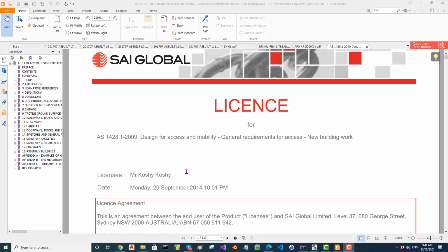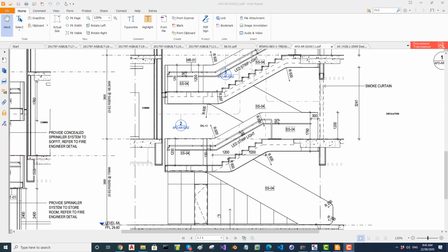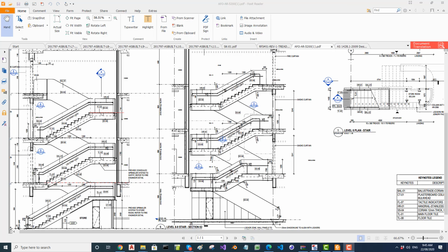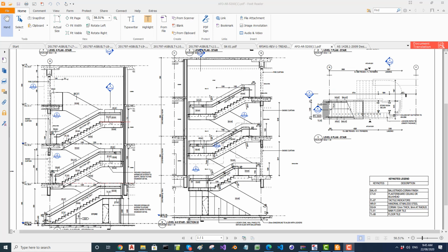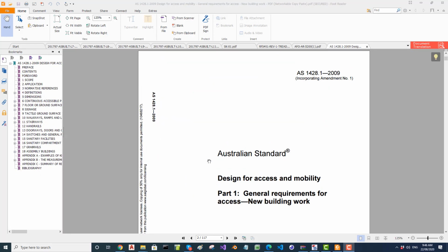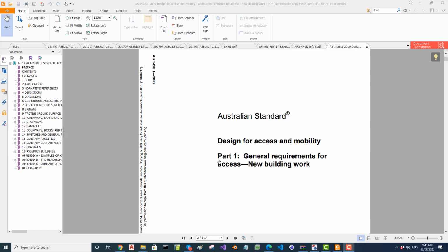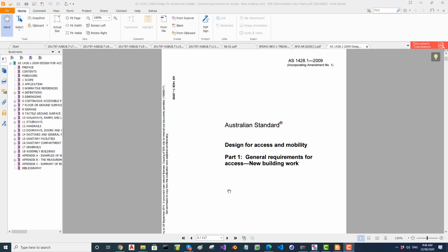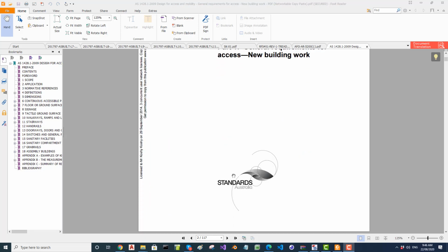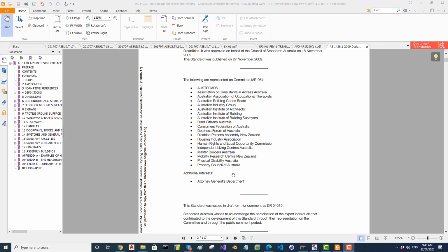First thing to know, hence, is under what code does the stair fall. Different standards, somewhat different requirements. This particular stair falls under 1428 because this stair is used by public. It's not a maintenance stair. So most of the time this is dealing with the stair widths, the rise, the going, the handrail height, the gap between the handrail and the wall, the slope of the stairs, and whether stairs are widening or narrowing as you come down. There are requirements there. There are also requirements about stair overlap. They are different for 1657 and 1428. A lot of things are common, but some things are different.